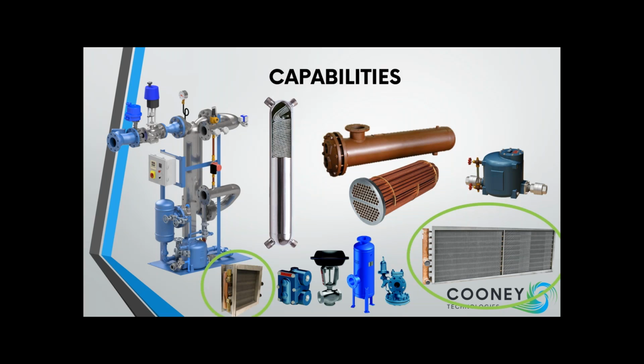Next, we want to show you some steam coils. The coils we have up here are steam distributing coils. You can see the 1-inch steam distributing tubes on the left-hand manifold. On the coil on the left side, you can see our Cooney freeze block technology. It shows the built-in vacuum breaker and our patented freeze block technology, which you could install on your steam coils, and you could really eliminate problems with freeze damage with condensate building up and freezing inside your steam coil.